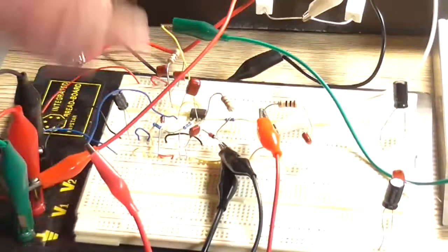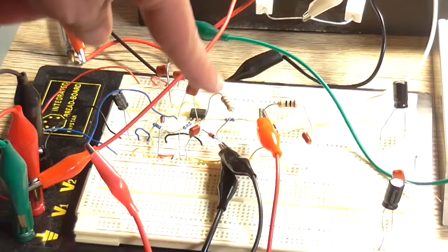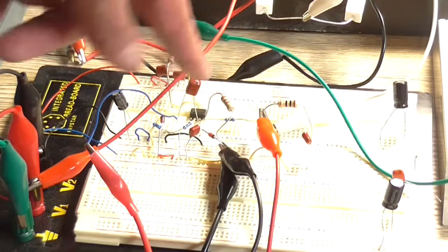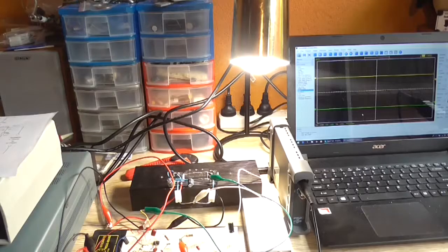Okay, as messy as that looks, I've got it all wired up. I've just got a simple Zener diode and resistor dropper for both the positive and negative rails to the OpAmp. Hopefully that's wired correctly. We'll soon find out. If anything goes bang, well, it goes bang. We're ready to test it. I'm going to leave it at 20 volt plus minus. Should be enough for the Zener diode to work.